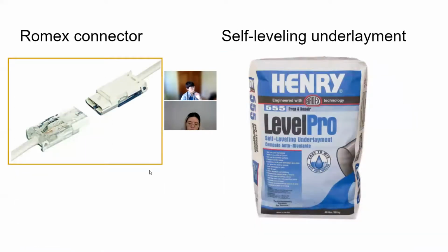And then when it comes to junctions, we've had some experience with this with the Solar Decathlon house, where we had 5 big pieces that needed to have Romex disconnects and reconnects when we were moving this house in pieces. We even had refrigerant piping connects and disconnects. So I'm familiar with products like the Romex connector you see on the left, and I'm comfortable with all the different piping and wiring connections implied by the ADU design. Structural would be easy to do if you create little panels to get to all the hold-downs or anchor bolts you'll need throughout the process. And then self-leveling underlayment is a possible solution on the right side.